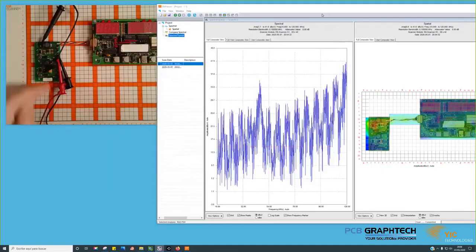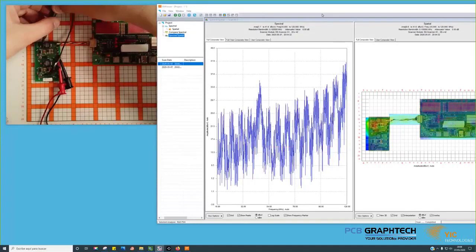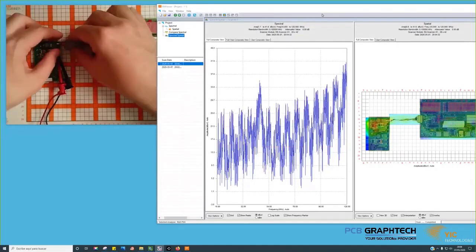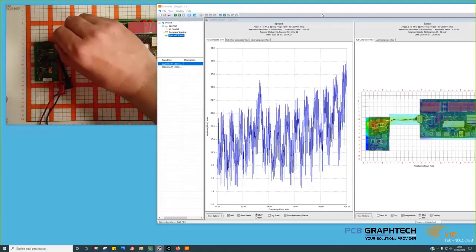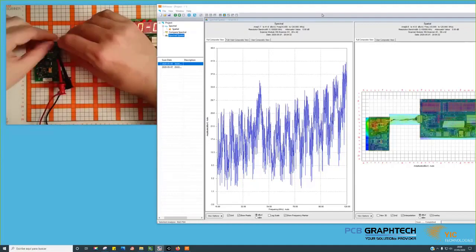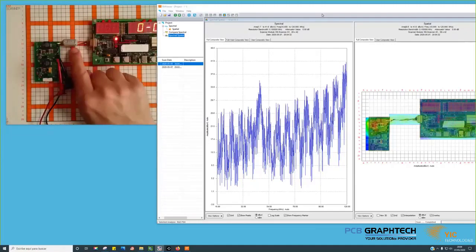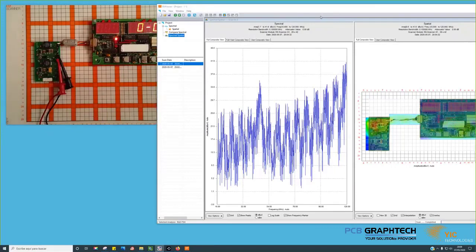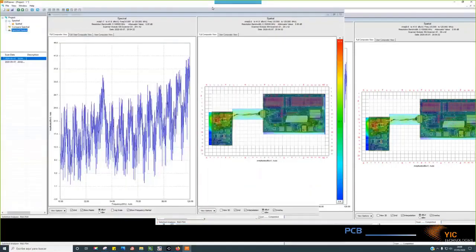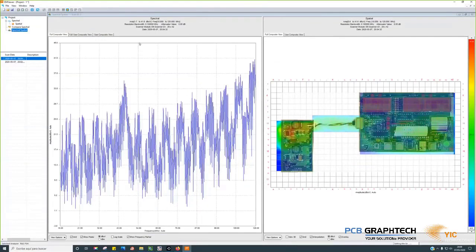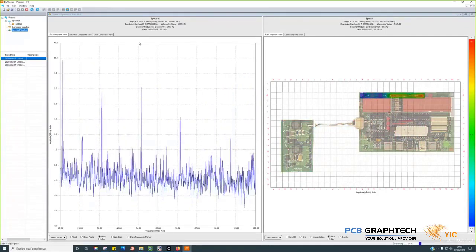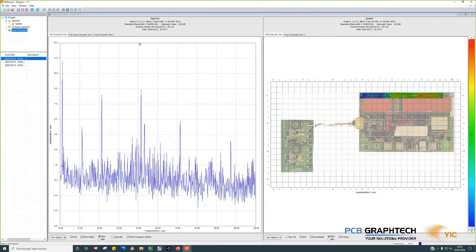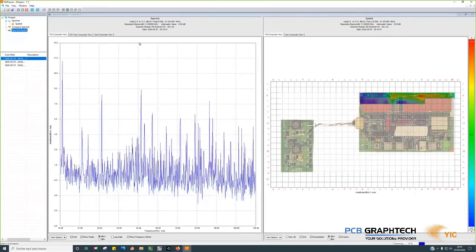And one solution, a typical solution in many products, is to introduce some kind of ferrite. No? So you go to the catalog of ferrites and you select a ferrite that introduces impedance in the frequency range of interest. So let me scan the board, same board, with the ferrite in place. No? Now I'm going to scan again. And we will be able to change the scales so that we can compare what happened with or without the ferrites. Need some patience.